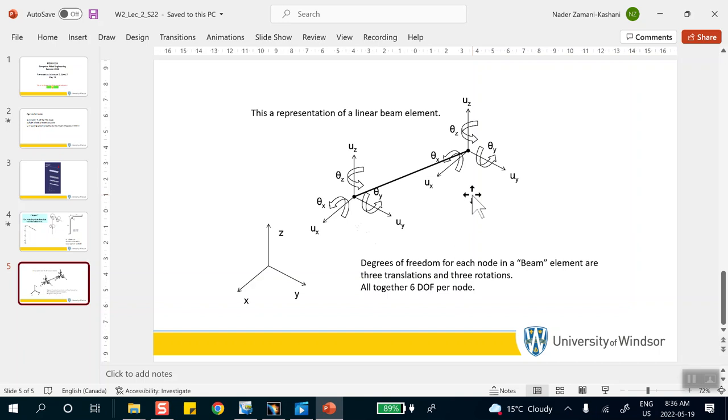In other words, there you talked about rotation. In beams, you talk about rotation at the node, at the point in the beam, okay? Basically, the angle that it makes with the horizontal. So every node of a beam element has 6 degrees of freedom, 6 unknowns, okay? A two-noded element has altogether 2 nodes times 6, 12 unknown variables associated with that one element.